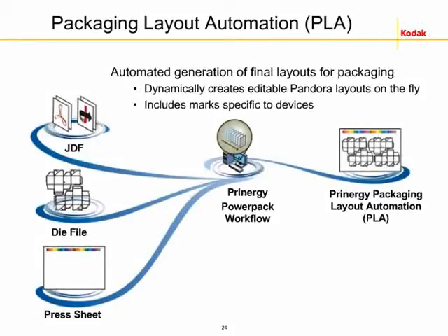One last thing about Pandora, I'll come back for one second. The other thing is, since Pandora is integrated into Printergy, you're not ever working with a composite file. There's never a file that is the entire layout stepped together. So if you have three different one-ups, and you have 3 lanes of 6 around, you don't have a file that's 18 one-ups long. It's actually just all metadata. And then Printergy actually assembles the layout at the last minute when you want to go to output. So you're not creating multiple files or composite files that are moving around the system. You're actually only giving it instructions that Printergy then stores as a JT.